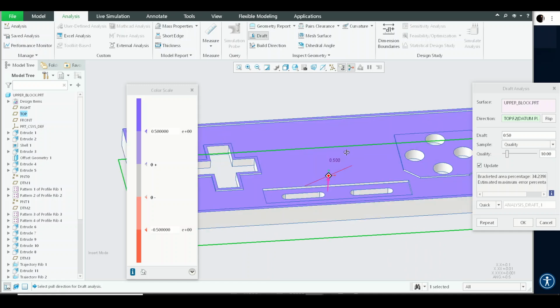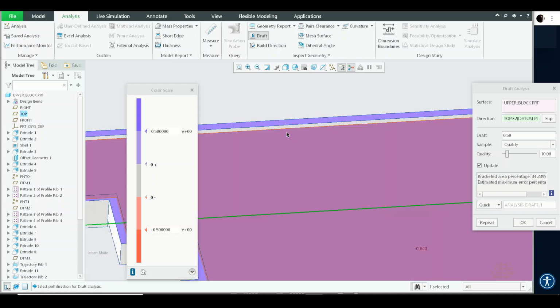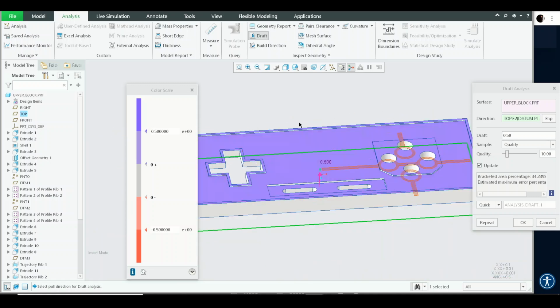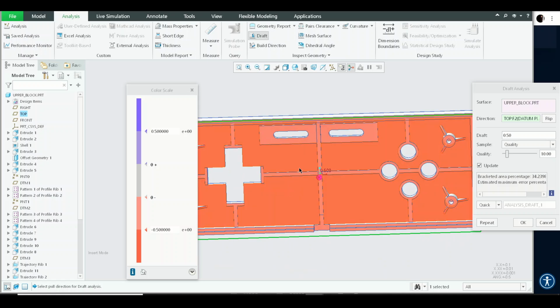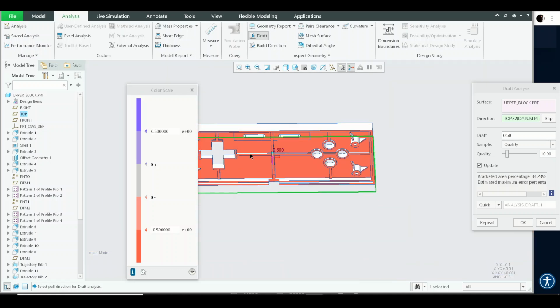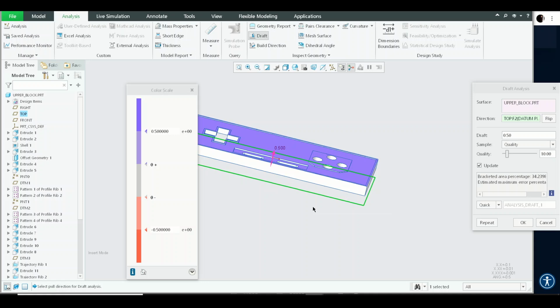and just see what is the color on the top. It is blue shade. So do something to the vertical walls and see that whatever is visible on the outside should be blue color. This is a simple trick I'm telling you, so that you're getting rid of any undercuts. And if you're having a red color inside, then whatever vertical walls you have in the inner regions must be in red color. Just try to go with this, and automatically your mind will set accordingly. You'll understand from the manufacturing point of view as well, like okay, this is the direction, then this is the draft required for me. But as a beginner, you can just assume this trick and proceed.